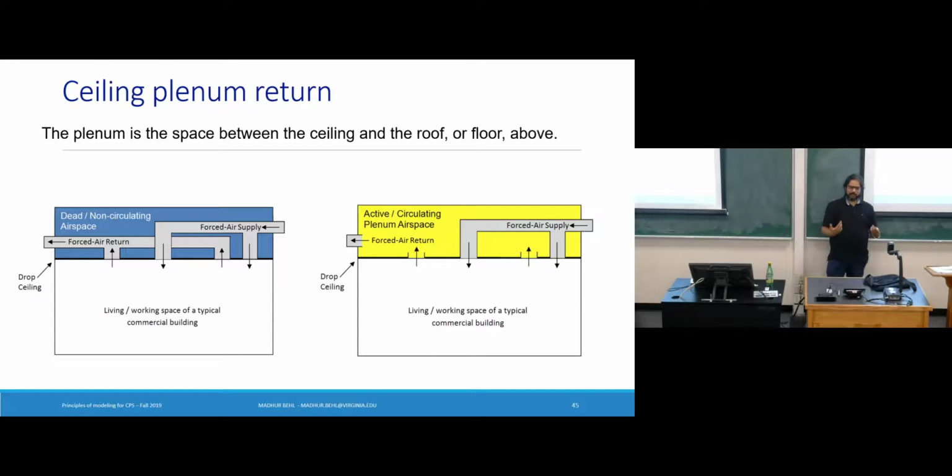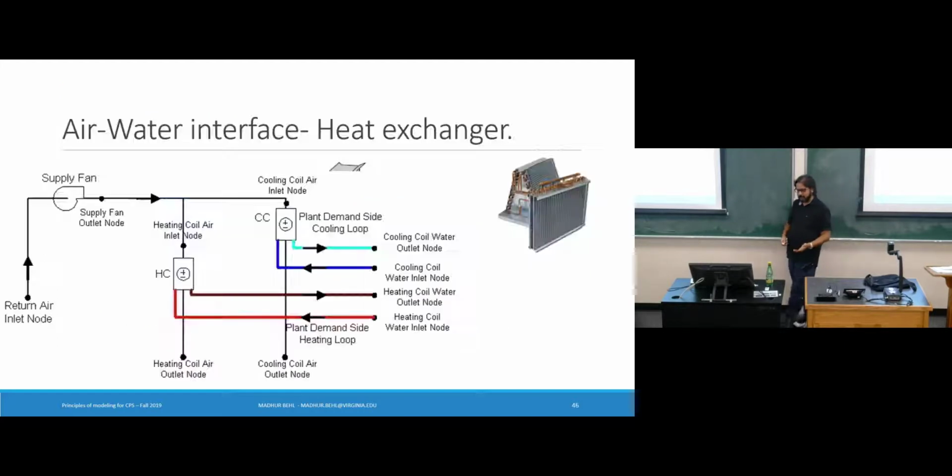But this air handling unit doesn't want this hot potato either. It's going to discharge that heat that it has into a water system, especially where we have this cooling coil. Right? So the interface in the air handling unit is this air-water interface. So once again, you get this return air back from the rooms. This return air is going to be at a higher temperature than 55 Fahrenheit because that's what it has done. It has taken the heat out in the zone.